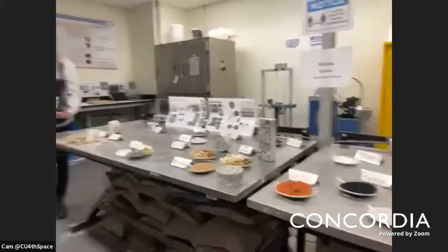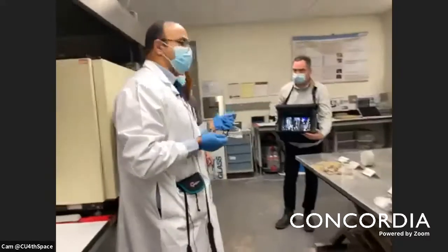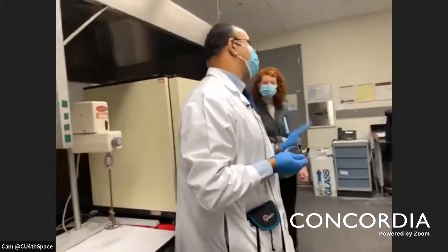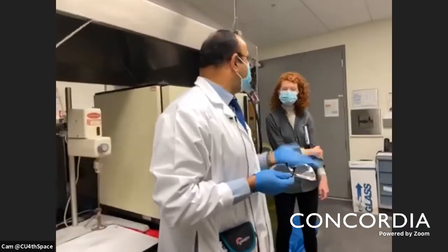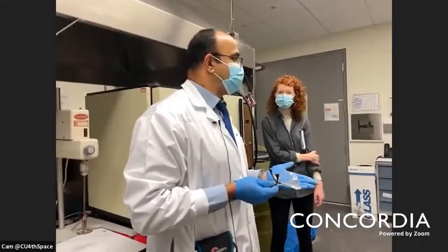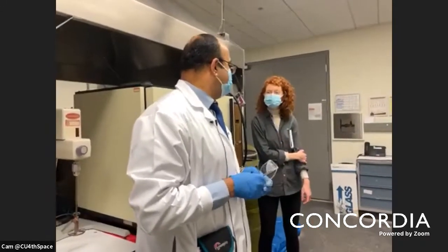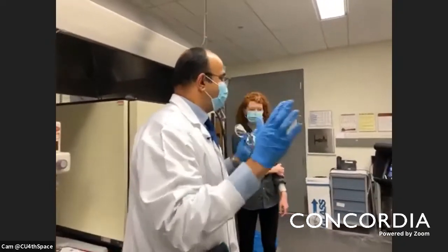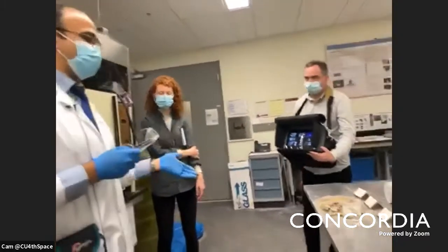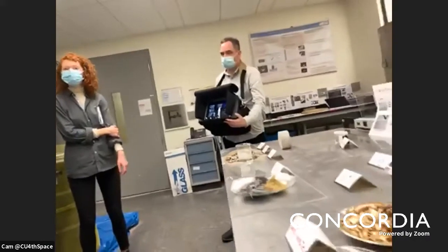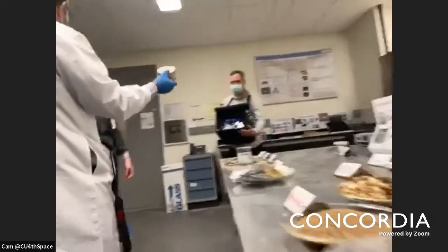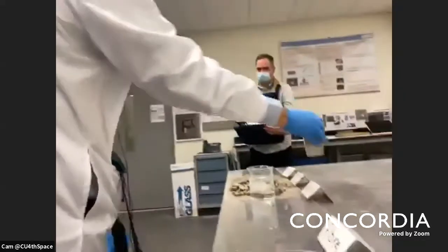Phase change material contains paraffin, and this paraffin, once it comes in contact with cement, is going to stop the hydration and stop the strength gain. So how are we going to deal with this problem? This is another aspect. Behind each of these materials, we have science running to make it usable, and we can implement it in concrete to maintain the final product, which is a very solid material that can sustain for a longer time.